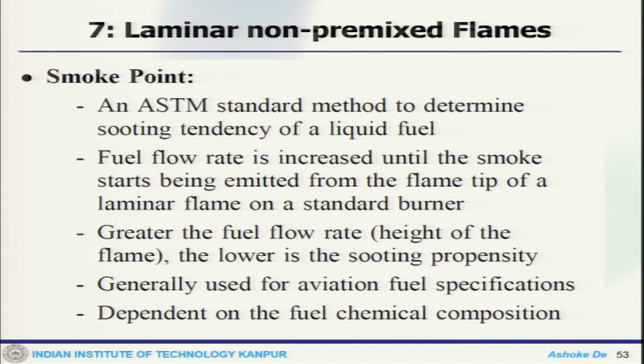Now, the smoke point: there is an ASTM standard available to determine the sooting tendency of a liquid fuel. That means every liquid fuel can be characterized based on this standard. The fuel flow rate is increased until smoke starts being emitted from the flame tip of a laminar flame on a standard burner.